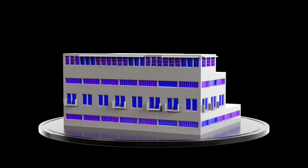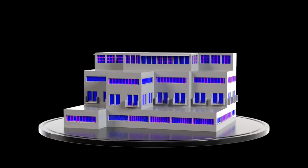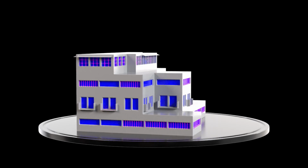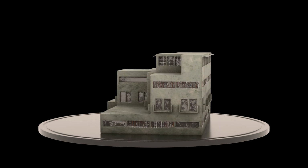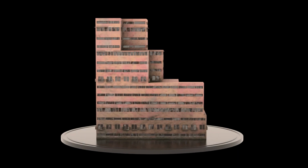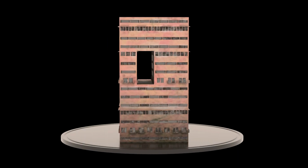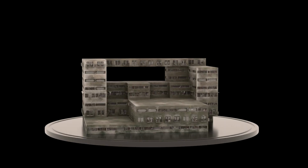Then by using the same voxel-based remeshing technique, I'm able to transfer the color data from the primitives in the separated mesh to the primitives in the voxel remesh. The texturing then becomes a lot simpler, as I'm able to use these colors to mask out different parts of the textures. Within Arnold Render Engine, I'm able to export the vertex colors from that output color set and use those to drive the masks. The asset may be used in Houdini Engine with a simple, intuitive interface for user parameter input, allowing the user to customize the output shape as they desire.